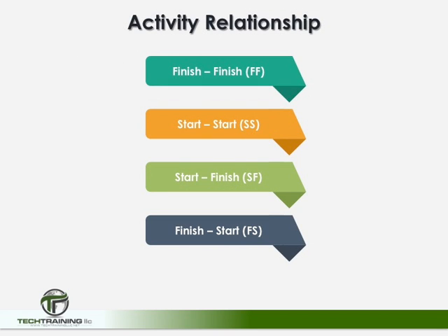So as you can see, activity relationships are extremely important to the construction schedule. They can be confusing. But once again, this is the importance of planning out the activities as discussed in previous segments of this course. Understanding the relationships between activities and defining activities are critical steps before beginning the construction schedule. Now, moving forward for the purposes of this presentation, all activities will be presented in the finish-to-start relationship.